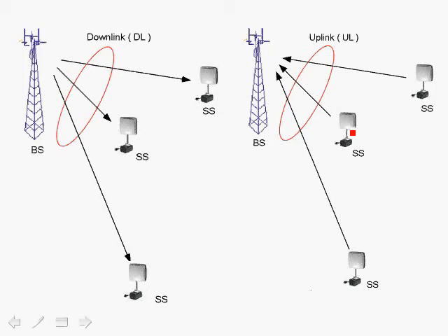And one thing that the base station is going to try to figure out during the initial ranging is the timing offset required for the subscriber station, so it can program that into the subscriber station such that all subscriber stations, when they transmit, have a time alignment when their OFDM symbols are received by the base station.